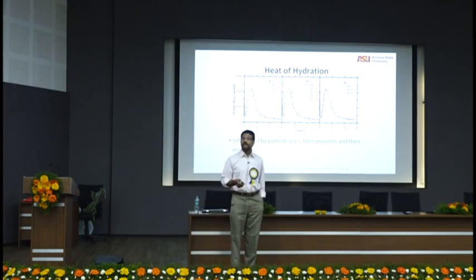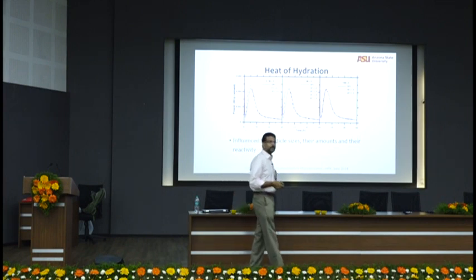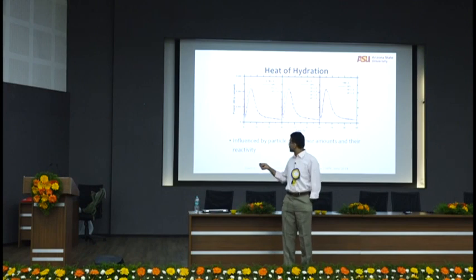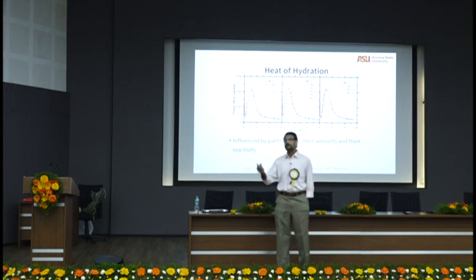Oh, cement content has to be increased to 550 kilograms per meter cube because temperature is going to be 16 degrees Celsius. You don't have to. You do not have to do it. You can tweak the system slightly, still be sustainable, still reduce the amount of cement.